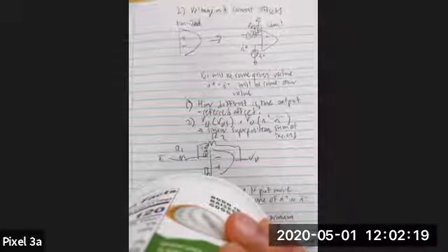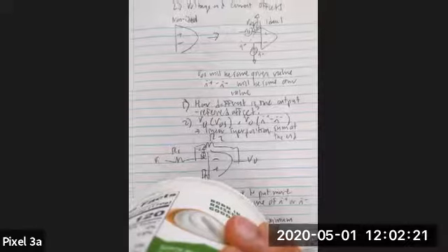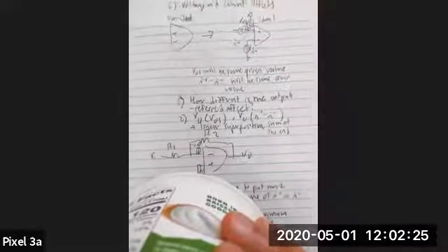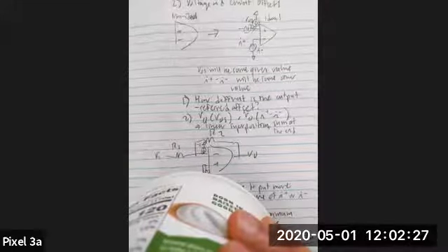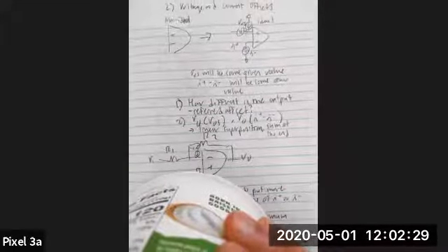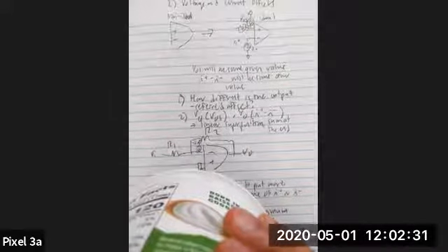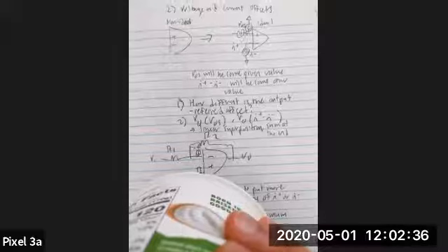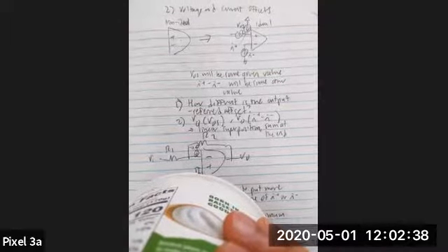The current bias is actually just the amplifier drawing current at steady state when it's operating, when it's being biased internally. So that's something we have to account for when we're using it, but it's not something that we need for it to necessarily work. Okay, that makes more sense.